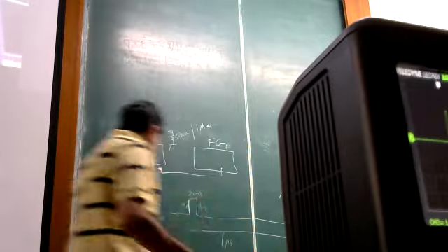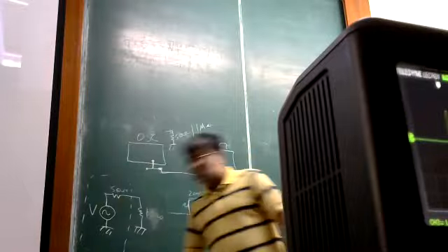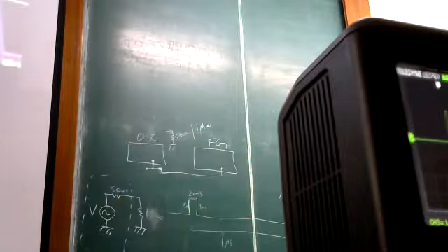I have set the instrument to 1 volt peak to peak here, but I have not mentioned that the output is high impedance. So you can actually make both of them compatible. Right now they're incompatible because this is expecting a 50 ohm load, but I have actually put a 1 mega ohm load. The difference is that in the instrument, when I change the output load, it's just a factor of 2 multiplication in the display.